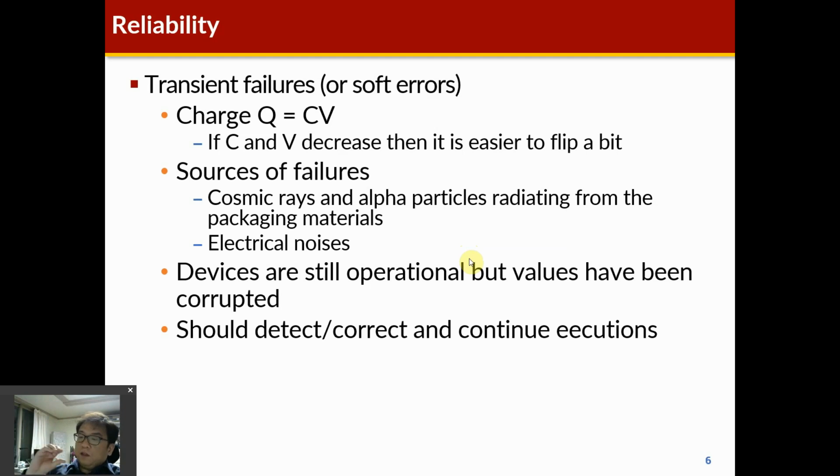Then if the PMOS is off and the nMOS is on, this charge is dissipated to the ground of the circuit. So basically the CMOS circuit has capacitor devices, and the charge is charged and discharged from this capacitance.